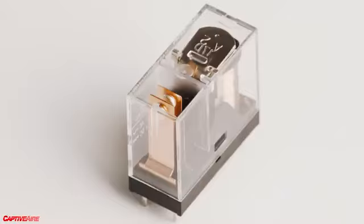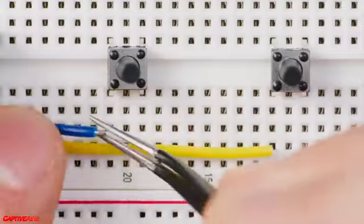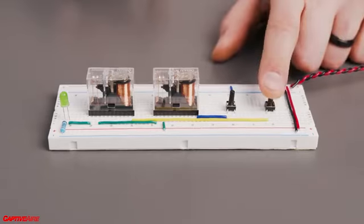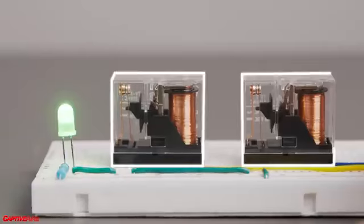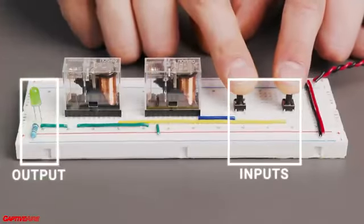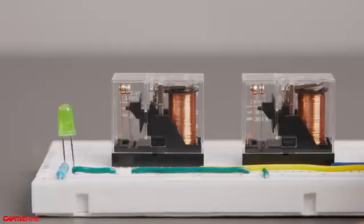Well, what if instead of having to flip switches by hand, we replace these manual switches with relays? Now we can use an electric signal to drive the relays open or close, or off and on. And you can see that this matches our first scenario, where in order for the light to turn on, both relays had to be on. You can still think of pressing these buttons as a way for me to change the inputs and thus get different outputs. But instead of a person pressing these buttons, they could just be electric signals coming from somewhere else.